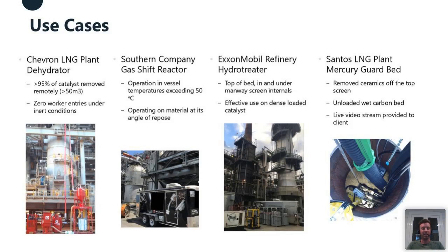At another site, a gas shift reactor, we saw the catalyst heat up really quickly, and in fact we melted some of the prototype screws. We've taken the lessons to develop higher rating screws, and we've just developed some aluminium ones. But that highlighted the fact that I heard stories of people standing on the catalyst and just running for the ladder when things like this happen, to avoid it melting through their shoes.